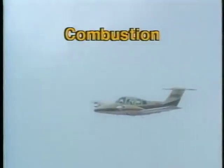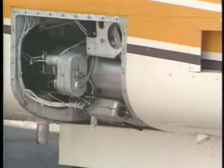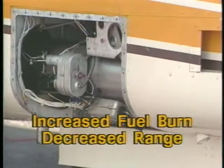The other heating system is the combustion type, which is like the gas furnace in most homes. This type of heater is commonly found on multi-engine airplanes because the location of the engines make heat exchangers inefficient and impractical. This system uses a blower to force hot air from the combustion heater to the cabin. Although combustion heaters operate independent of the engines, they rely on the same fuel supply. Therefore, you should plan on increased fuel burn and decreased range when using this type of heater.